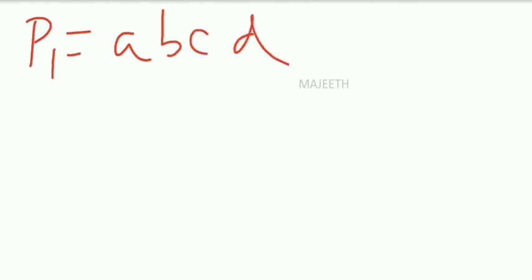We don't have any other gain. So the number of forward paths K is equal to 1. The first forward path gain is ABCD. Now we write all the individual loops. Why are we finding the individual loops? Because del is equal to 1 minus the sum of individual loop gains.